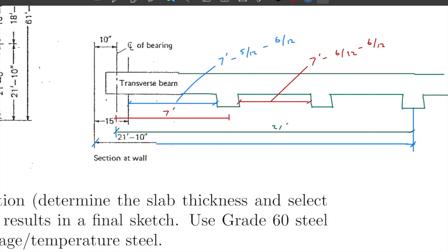And so here's the beam going embedded into the wall. And then it's showing you where the center line of the bearing is, right? And so that's what this is showing us right here. There's the center line of the bearing. So this thing, there's the beam sitting in here, and it's resting on a bearing, right? And so that's where its effective bearing force would be coming in right there. Why that's important is because that tells us, right, when you draw shear and moment diagrams and stuff like that, it's going from the center of the support to the center of the support. So it's the center line of this support to the center line of this support over here.